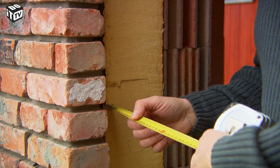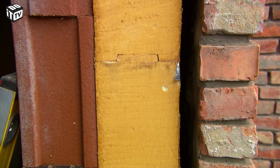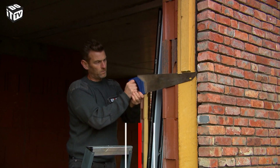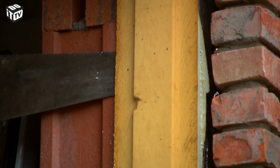So, to enter the production size, we always add 2 cm to the left, right, and top. But we are going to let our masonry and insulation recede by 5 cm. This is because we can further insulate the window with PU foam afterwards. Here and there's still some excess insulation. You can easily hide it with a simple handsaw.